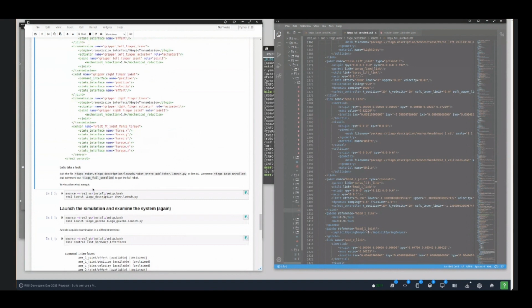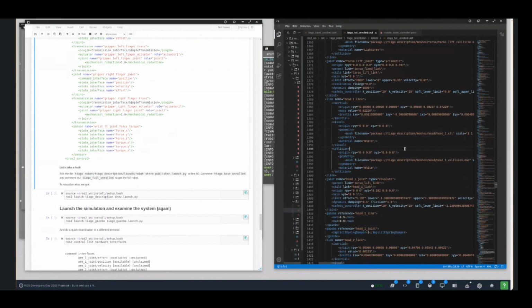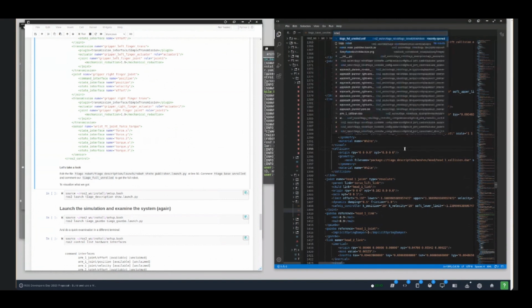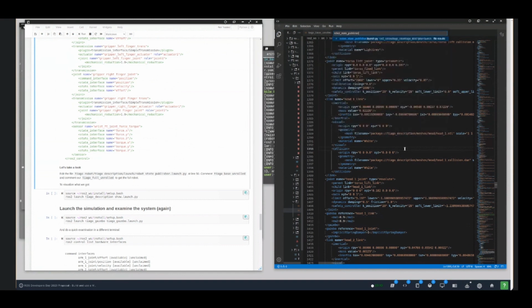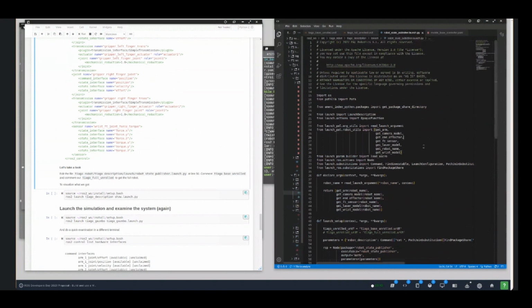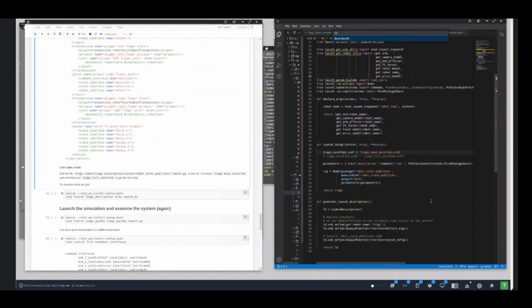Now that we know this, we actually need to put this into action. For this tutorial, I took full advantage of the already existing ROS2 setup of the Tiago, and I just hacked it a little bit so that we don't have to work that much to make things work. But I'm actually explaining how to hack it back, so that we get the rest of the robot back. So we need to open the robot state publisher launch file and jump to line number 50. All of this is also written in the text.